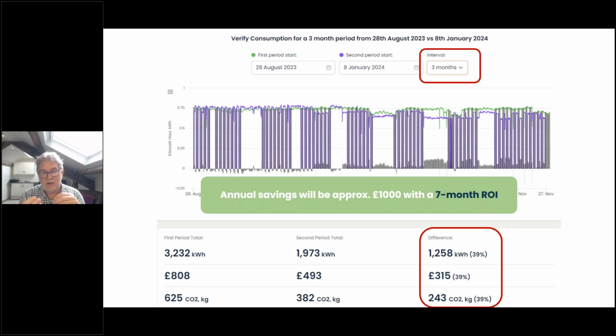And the client's rolled this out to the other 6 air handling units on site that aren't required during non-working hours. So pretty straightforward. Spotted that it was on 24/7 and took some easy to fix measures to put some form of switching into place. In this instance, it was our Internet of Things monitor driving a contactor that takes out the handling unit during non-working hours.